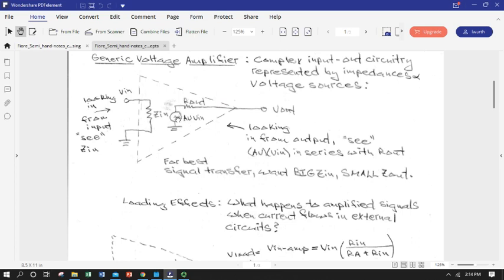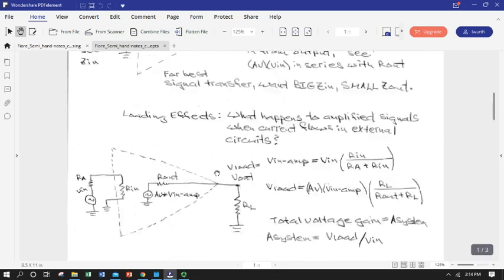When you're doing a current measurement, you want your impedance very, very low so you're not introducing a voltage drop into the circuit when you measure current over your shunt resistor. So that's kind of like the output of this generalized amplifier. You want R out low, the same reason you want your shunt resistor in your meter low to make a current measurement. So let's take a look.